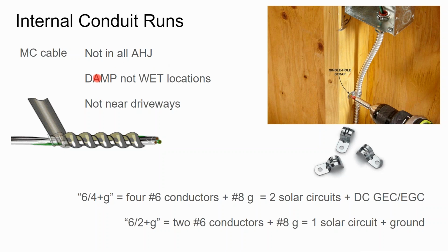So if you're under a covered awning, having a couple feet of flexible metal conduit is not going to be the end of the world. It's just some authorities having jurisdiction are going to require, usually if they don't allow flexible metal conduit, they also don't allow EMT, and they're going to require rigid or intermediate conduit.